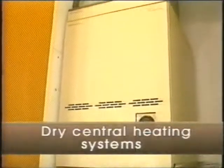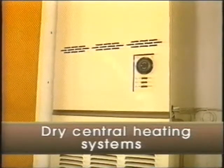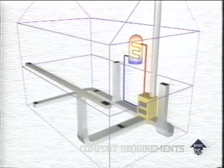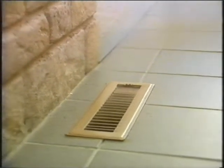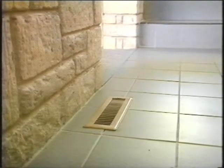Dry systems use warm air instead of hot water. Air's drawn from the house and blown through a heat exchanger. A fan then blows it on through ducts to registers or diffusers around the house. It warms a house up very quickly and maintains even, controllable temperatures. The size of the ductwork needed makes it difficult to fit into existing buildings, so you usually find it only in newer premises.